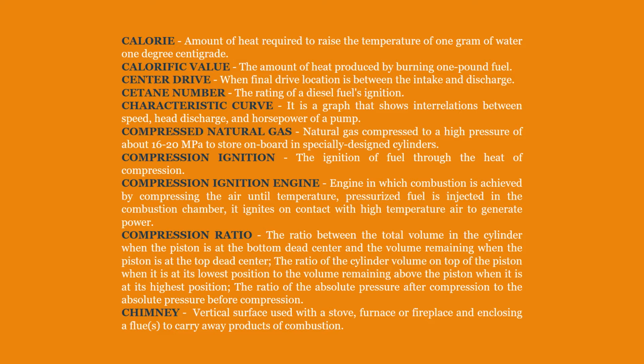Compression ratio. The ratio between the total volume in the cylinder when the piston is at the bottom dead center and the volume remaining when the piston is at the top dead center. The ratio of the cylinder volume on top of the piston when it is at its lowest position to the volume remaining above the piston when it is at its highest position. The ratio of the absolute pressure after compression to the absolute pressure before compression.